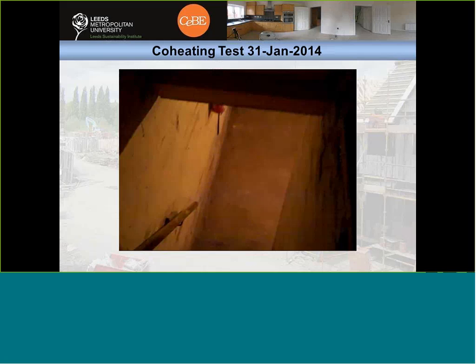This scheme on the right shows the basic principle of the co-heating test. So it is actually a quasi-stationary test. Stationary because we keep the indoor air temperature at an elevated level, for example 25 degrees. So we keep it at that level using the heaters and ventilators spread throughout the dwelling. Meanwhile we have the weather conditions. So we have stationary conditions inside, but we have dynamic weather conditions. So that explains the term quasi in front of stationary.